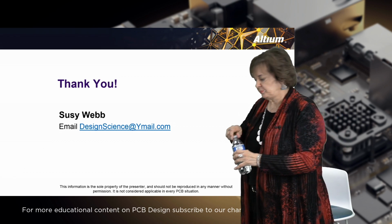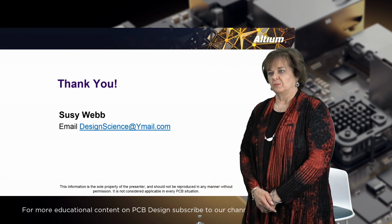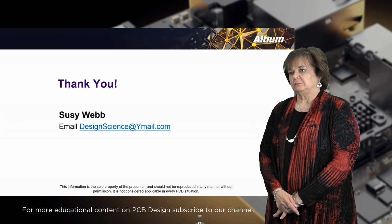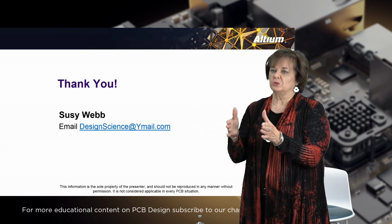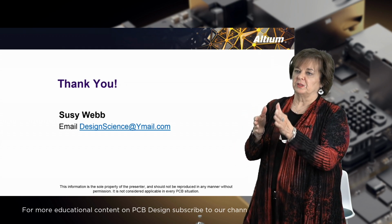One is from George de Castro, and his question is: can we play with ground vias to play with the current loop, trying to reduce the path? Well, you always want the ground via to be as close to the signal if the signal is changing layer with a via.